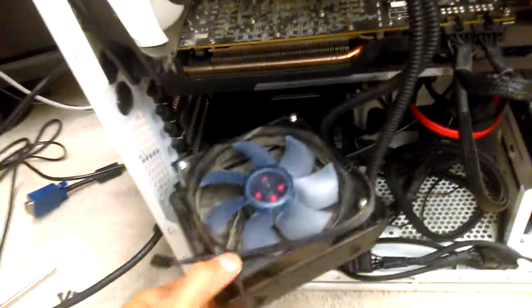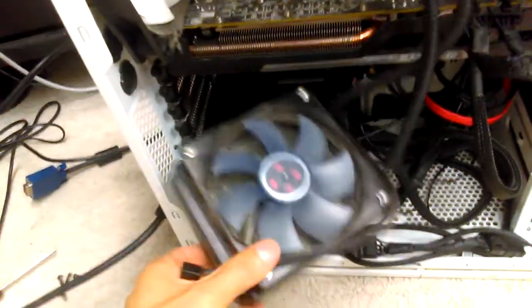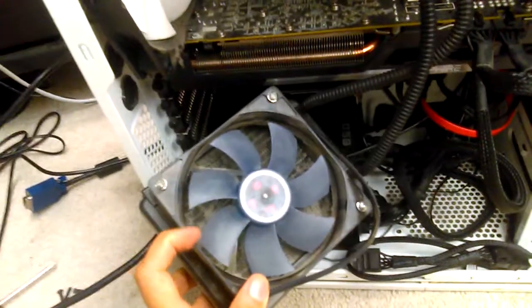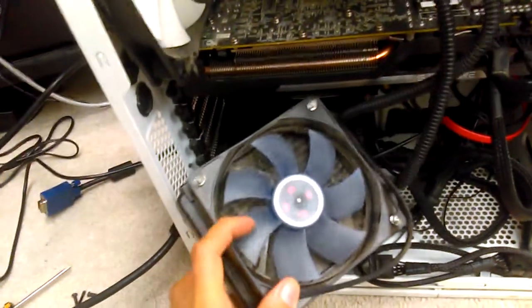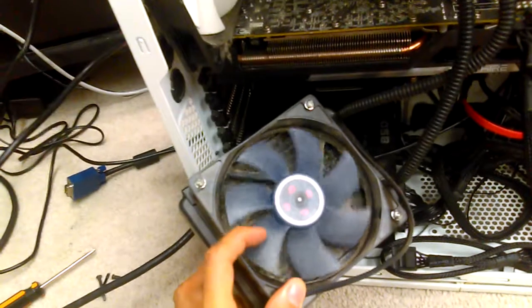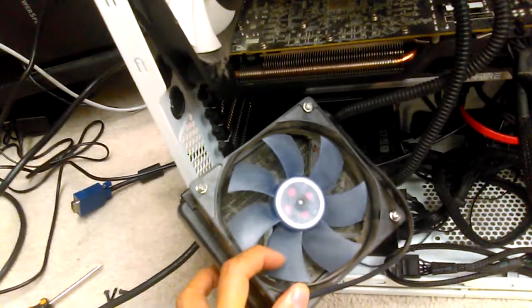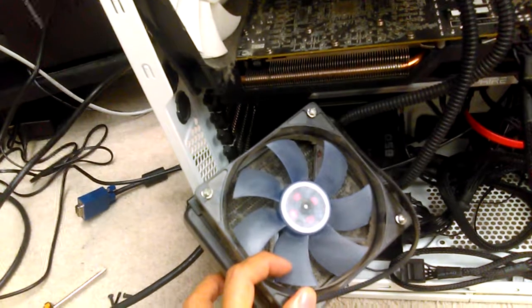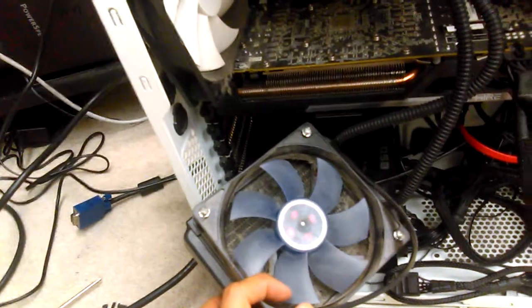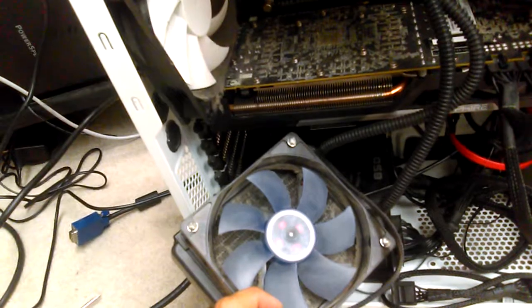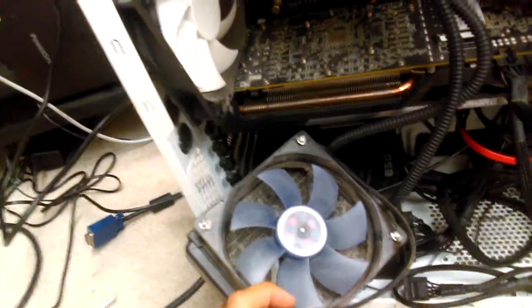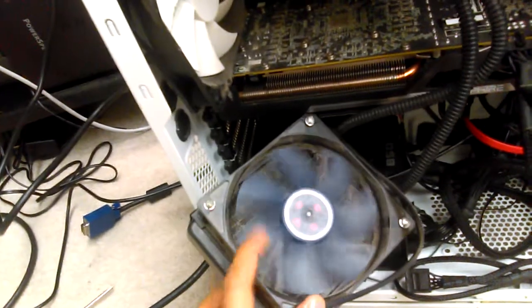Now, since this customer just wanted a diagnostic, I will tell him, I could even send him pictures, and I'll say, look, your radiator is caked with dust. Do you want me to fix it for you? If he says yes, I might charge him my full $80 fee, if not a little bit less, because I don't have to do much.